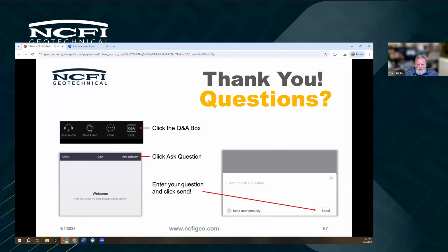I've done, just from personal experience, installing a radon mitigation system in some of the older homes here in Knoxville where I live, and they basically poured the concrete slabs right on the clay. So in that particular case, if you try to inject into that, it's not going to take the grout. And if you try to use dual component for that situation, you're going to move the slab. So if the conditions are right, the answer is yes. Yeah, and we have some contractors who very much specialize in utilizing single components to stabilize and seal basements or underground structures. So, yes.